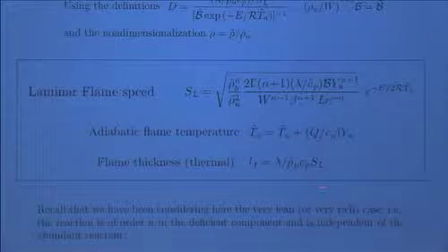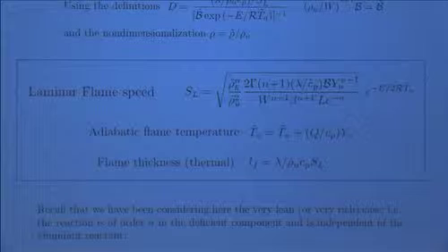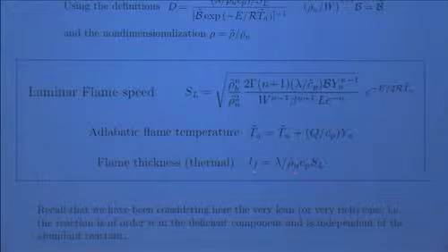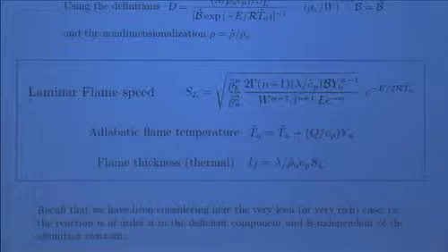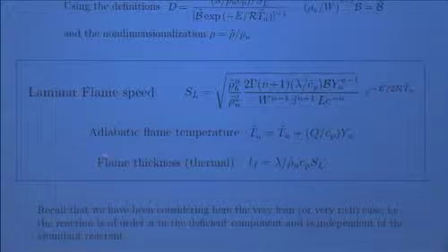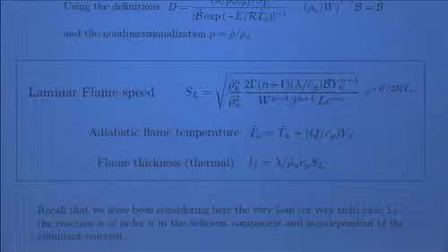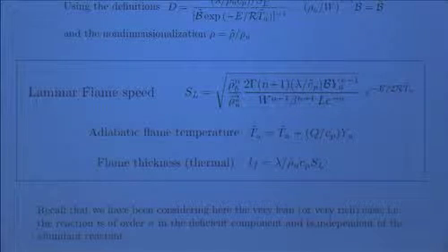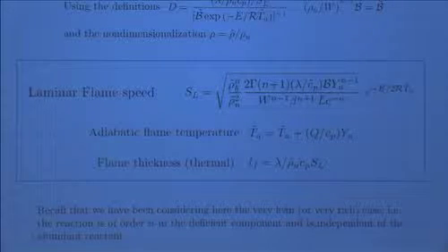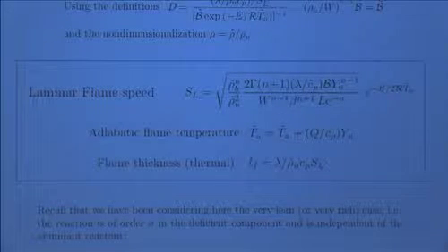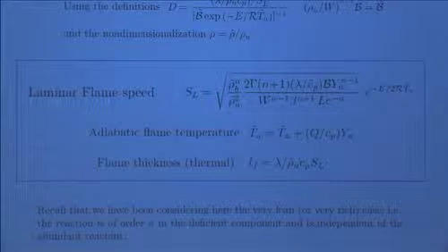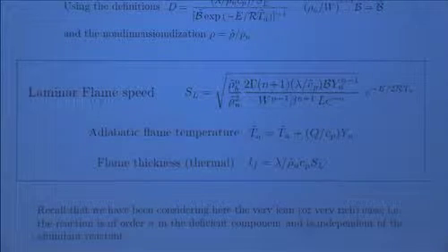But remember, it involved the laminar flame speed, so until now we didn't really have a full description or a full identification of the thickness. Okay, and remember that this was written for any reaction order n, but for only a single reactant. And I will tell you a little later how the same relation is modified when you look at a two-component mixture.